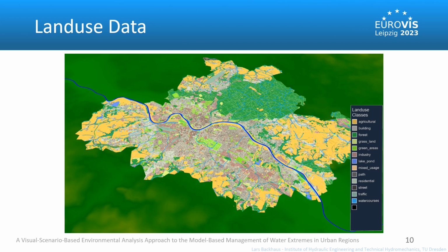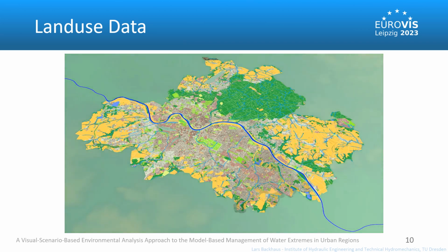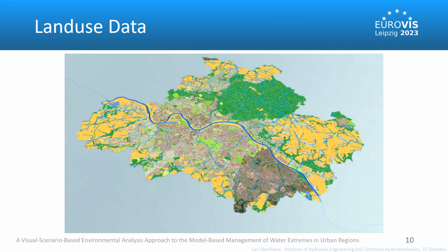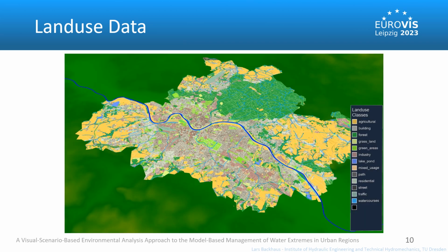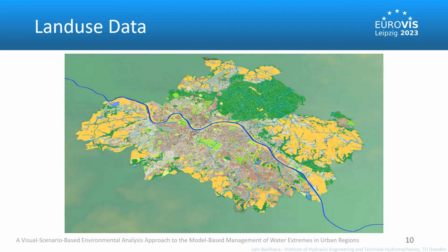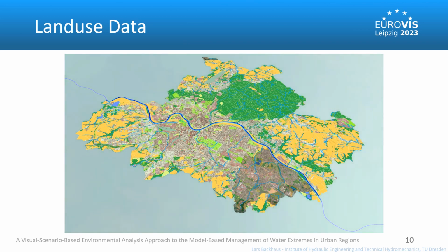Hydrologic and hydraulic models require various additional input data sources such as soil infiltration, evapotranspiration, or surface roughness. Therefore, publicly available land use and biotype data was processed. The land use data consisting of multiple categories of buildings, water bodies, urban infrastructures, and vegetation was clipped, merged, and dissolved with the transport infrastructure.